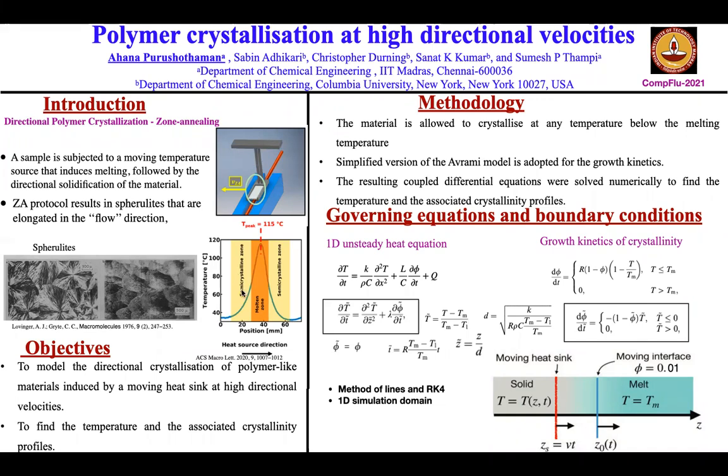So the temperature inside the material is shown here. We have a peak temperature, that is the point where this material comes in contact with this heated metallic rod. Therefore, that region of polymer gets melted. And on the two sides of this, we have the semi-crystalline zone.